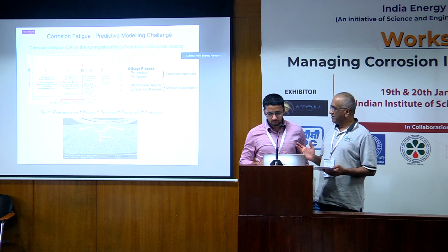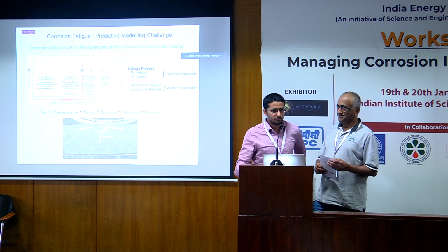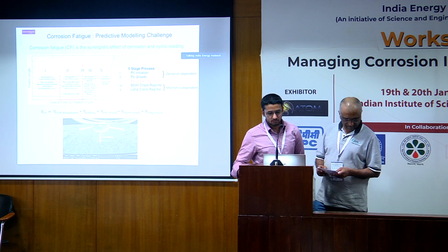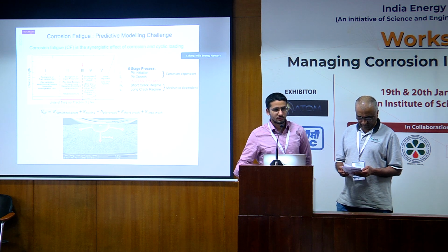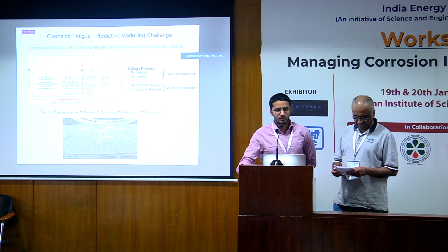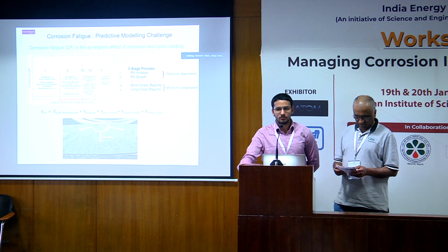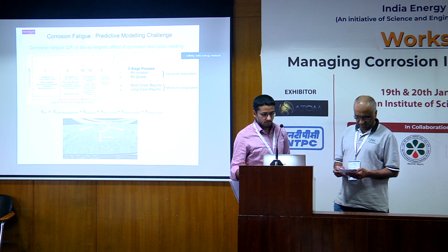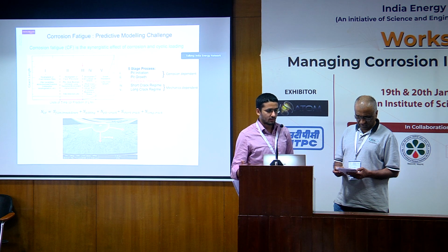Am I audible? Yes. I'm working in the nuclear industry, so a lot of the time we have issues where cracks are found and we have to demonstrate fitness for service. At present, we demonstrate it by using fracture toughness, which is based upon either linear elastic fracture mechanics or elastic plastic fracture mechanics.